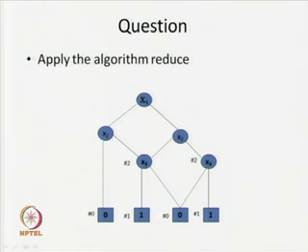So, these are not the same as the 0 and 1 nodes, and secondly, these two are at the same level x2, with the same variable x3 and x3. So, for the sub BDD, for both the 0 edges it is going to the 1 terminal, for both the 1 edges it is going to the 0 terminal. So, it will also get the same label with this particular x3. So, both are labeled with x2.